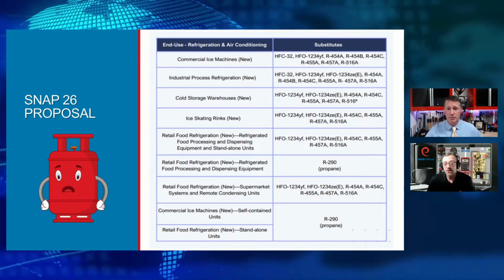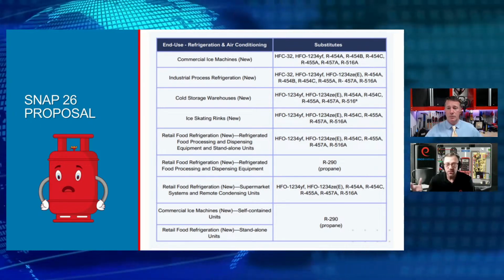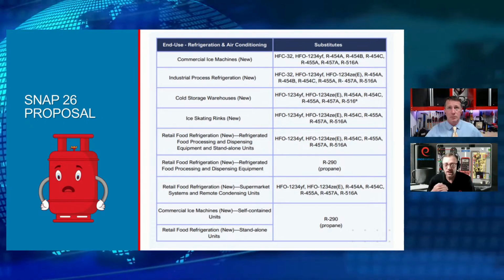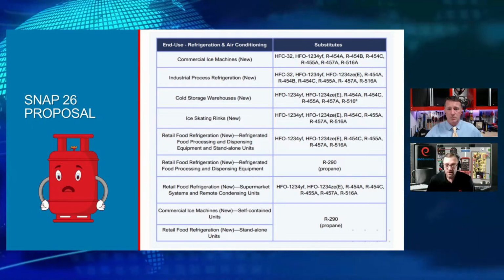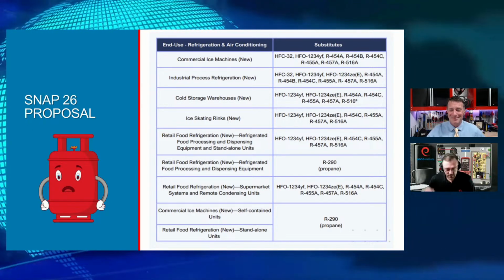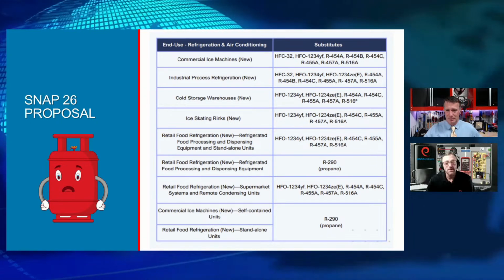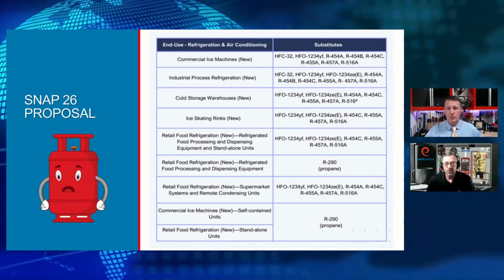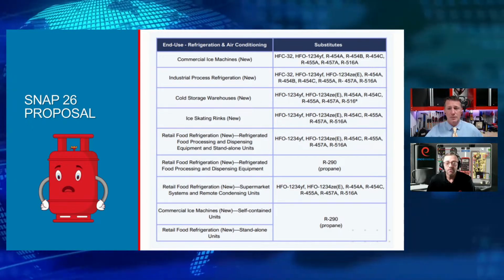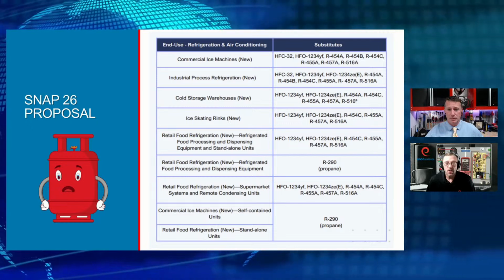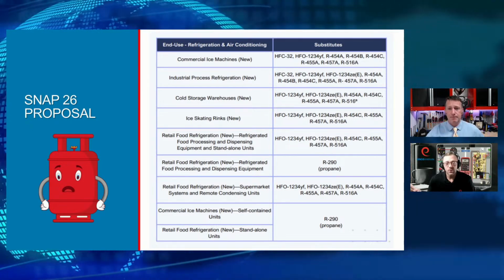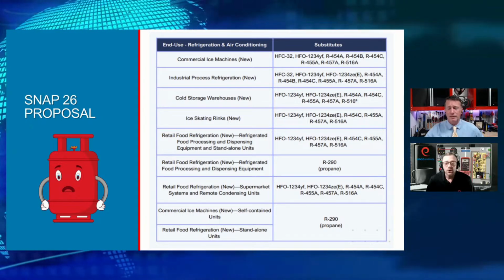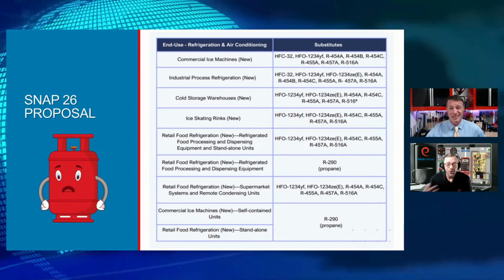That doesn't mean they can be used everywhere or anywhere, and there are what we call use limitations. So there are going to be charge limitations. It doesn't mean that I can use R290 at 15 pounds or 30 pounds. It is very specific. So when we get into what you mentioned earlier, the 2L, 2, and 3 refrigerants on the flammability scale, there are going to be charge limitations based on, one, the flammability, and two, the application. Is it a commercial or residential occupancy? How big is it? What's the free airspace around this appliance? Is it in a closet?